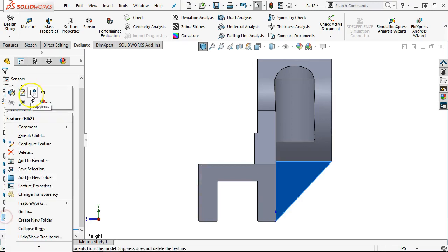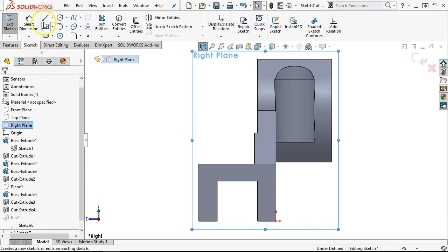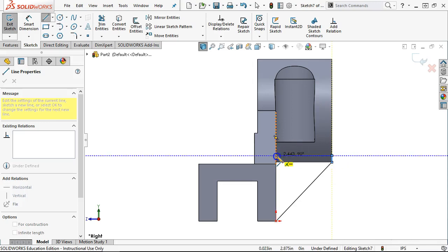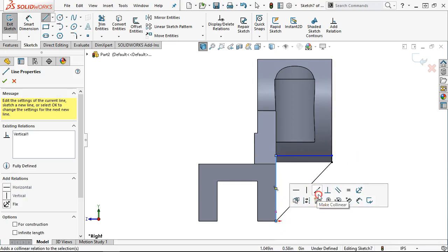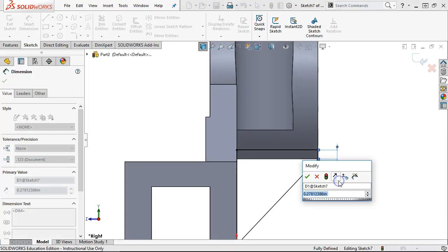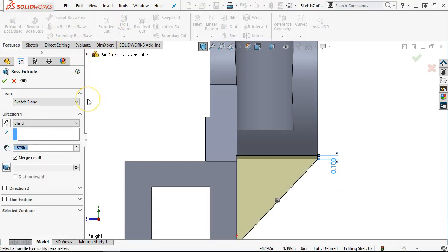Alright, so let's go ahead and suppress that one out, and in contrast, if we want to try and build that geometry, the CSWA3 example had that blend where I could go right to that corner. And then as long as I intersect in far enough and tie those back together, that's what I ended up doing, and then we extrude to 0.75, and that'll be a midplane.